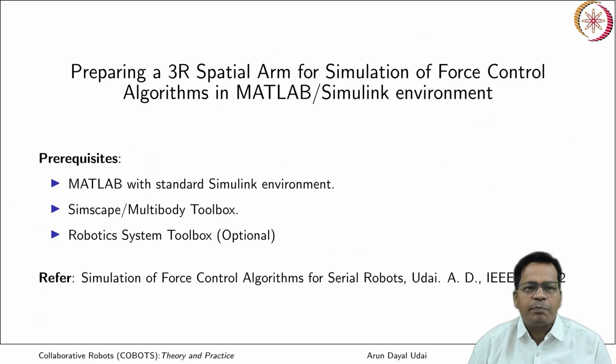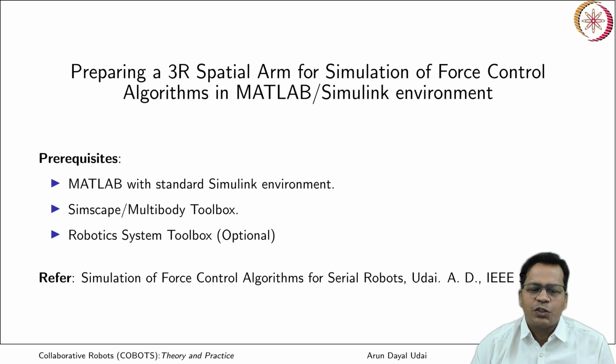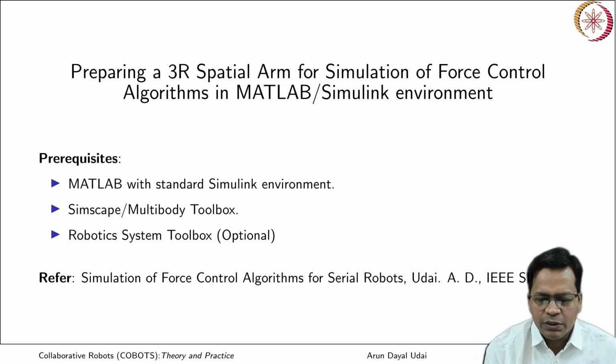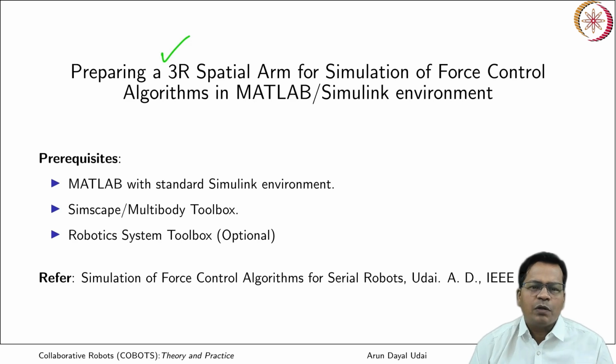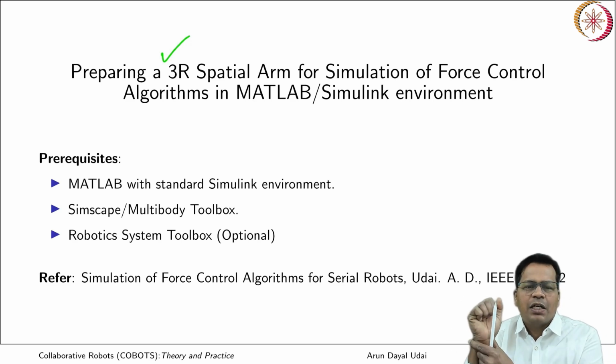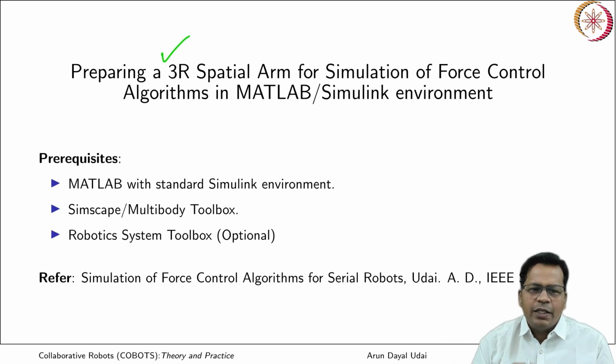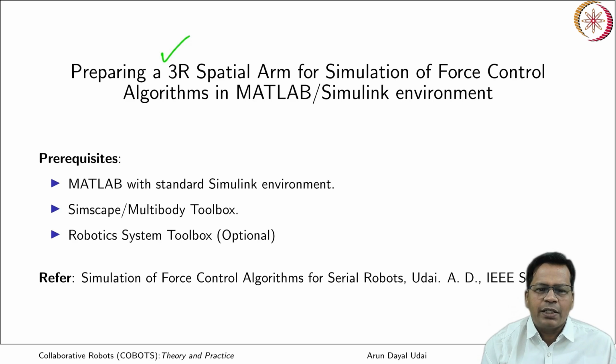Let us start preparing a 3R spatial arm for simulation of force control algorithms in the MATLAB Simulink environment. I have chosen a 3R spatial arm because most industrial robots or cobots are also 3R spatial arms up till the wrist. A spatial arm can attain any position in Cartesian space in x, y, z location.